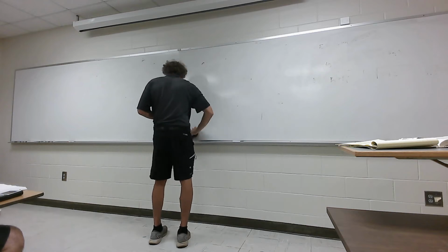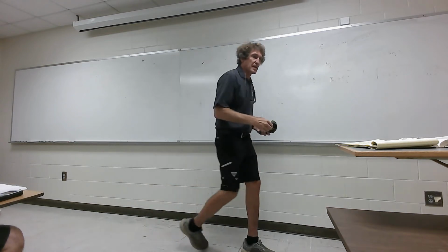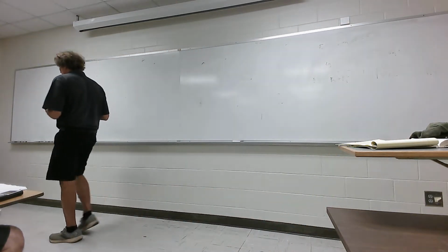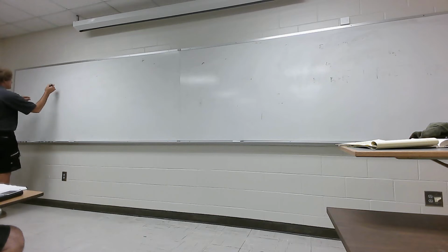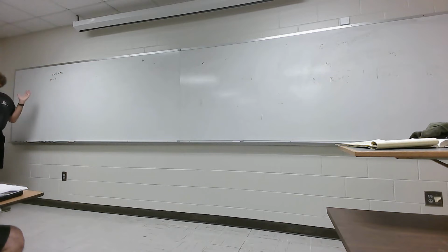So, if you have any kind of media and you see that sigma is zero, that's lossless. There's no losses. If you don't have a value of sigma, or there's an equivalent thing, you'll see that it's effectively a type of sigma for low loss dielectrics. You don't have any power loss.